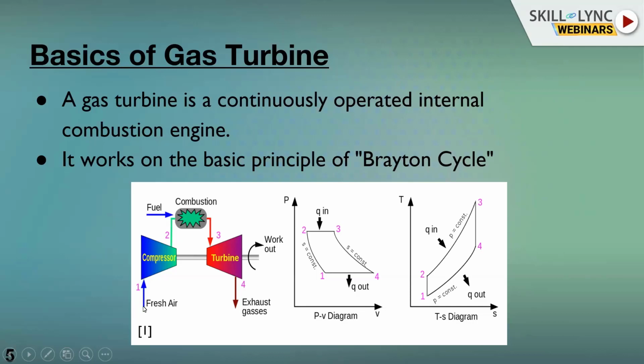Okay, so here first, fresh air is injected into the compressor, and in the compressor an isentropic process takes place where the air is pressurized to go from step 1 to step 2 at constant entropy. That means your entropy is not changing, so no heat or mass transfer is taking place at this step, but you are increasing the pressure. So you are basically pressurizing your injected air. Then the next step will be the isobaric process. An isobaric process is nothing but a constant pressure process. And where does this isobaric process occur? In the combustion chamber of the gas turbine.